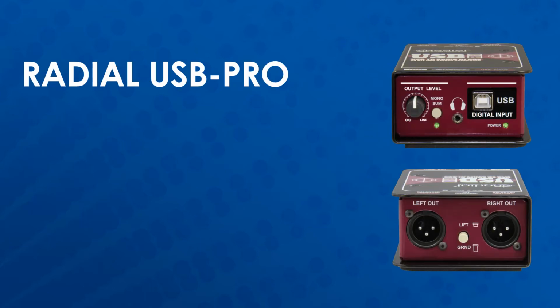Daktronics uses the Radial USB-Pro. Here we will cover the controls and connections. The output level knob controls the amount of signal coming out of the XLR outputs. When turned fully clockwise, it outputs line level signal and reduces in volume as it's turned counterclockwise.